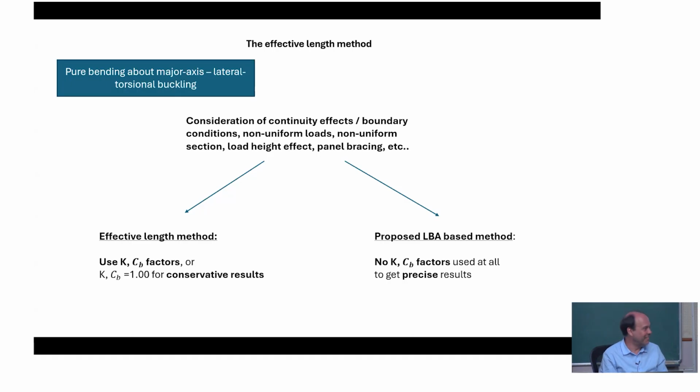Only if, but that if is not even checked. So it's not true that it's always 1.5. It depends on the type of roof system, on the stiffness of the purlin, and on a lot of things. But if you use Consteel, it's not even 1.5 that you have in the model. You don't even enter the 1.5. Nothing. Just build the model. If your purlins are at 1.5 or 1.9, it doesn't matter what you want, then it will be that. So these are two different concepts.